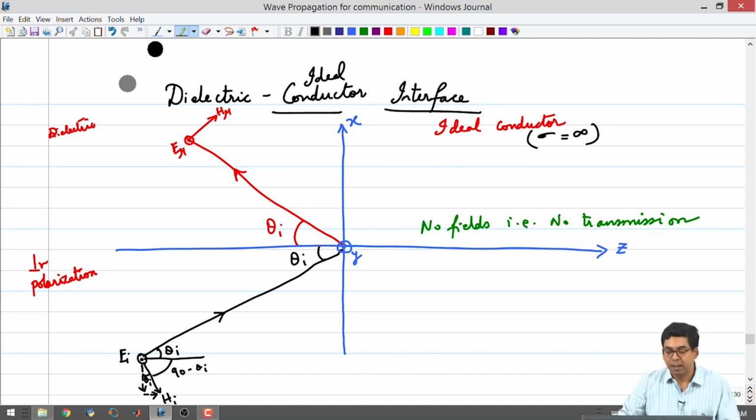And since this is a travelling wave in the positive x direction, in this configuration if I placed a second plate on the left side, there would be complete reflection from that plate and there would still be a net travel in the positive x direction, exactly following the expressions that we have written before. The consequence of this is that the wave is going to be completely confined between these two plates.